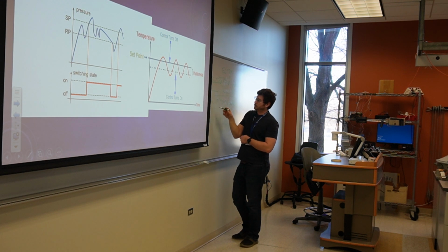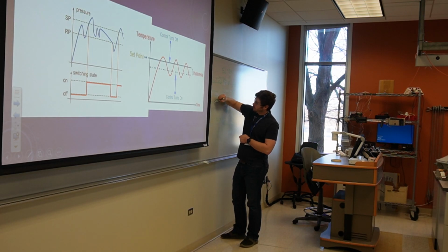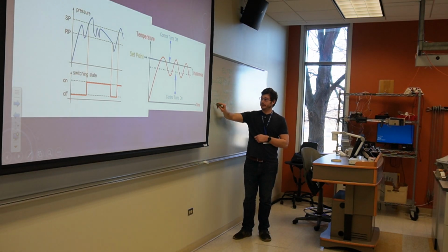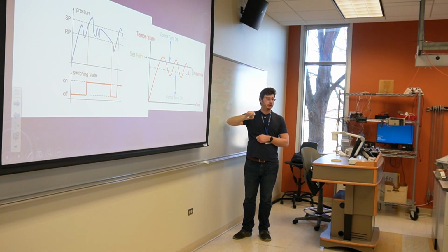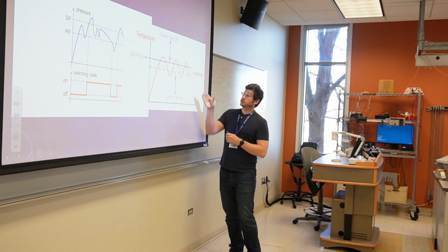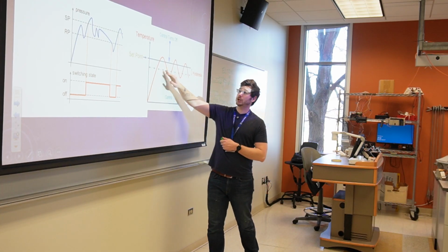We'll eventually cross it again, but when we do, we'll restore it back to where it was. So now we have distance again. So if we have our noise problem on the way down, if this is changing a lot, our set point's now all the way up here. We have clearance. We aren't constantly triggering it all the time. Okay, so this is the concept of hysteresis, and changing set points.